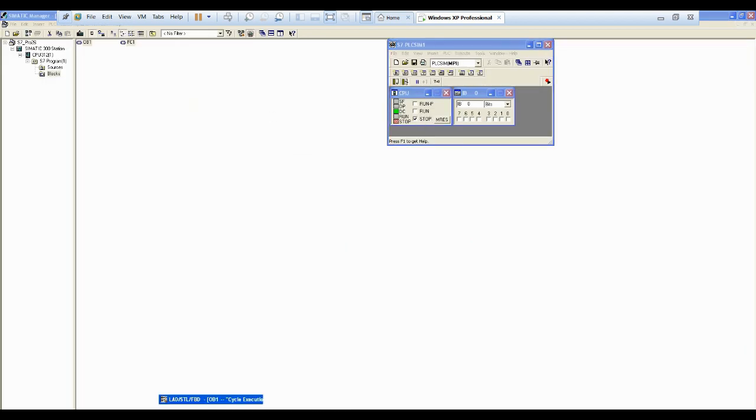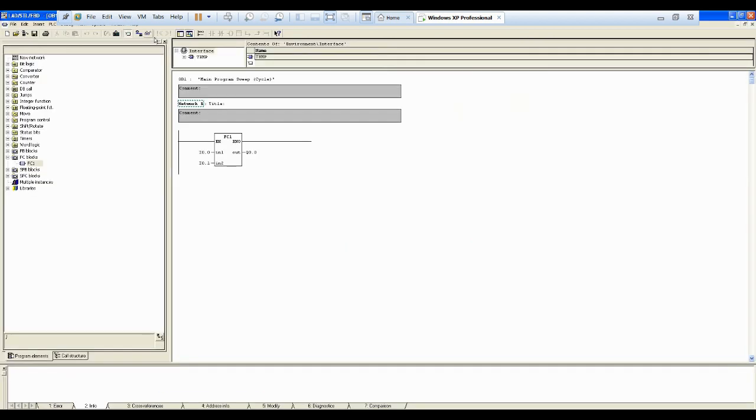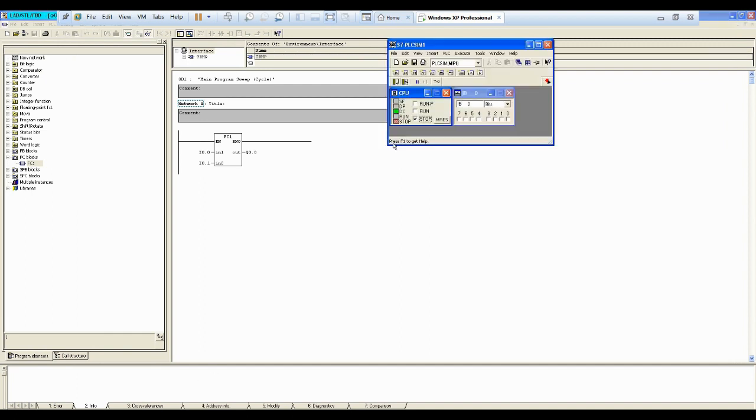After that, try to open up this watch sign. You have already downloaded both, and now when you run it, see, both are currently 0. So if we have one input, we don't have output because AND needs both inputs high to get an output. So if I click the second input here, I0.1, that is going to make our output true. So that is the FC.